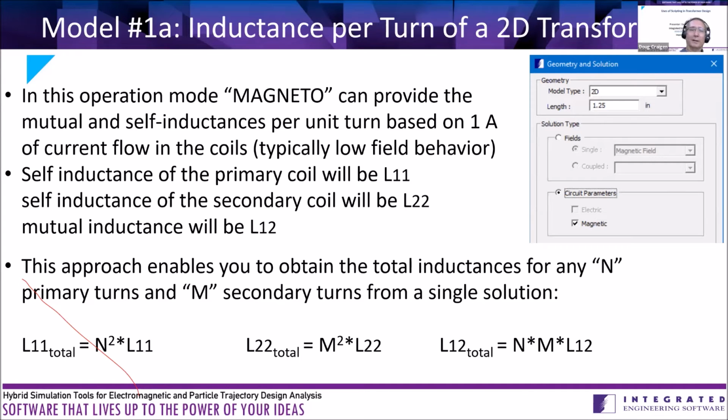So magnetically, some of the questions that we can look at have to do with flux linkage and inductance. If we do a calculation that's based on a per turn inductance, then we can simply use the number of turns later to scale it. So you can make all your wire gauge and those kinds of decisions later if you know your flux linkages and your inductances per turn.